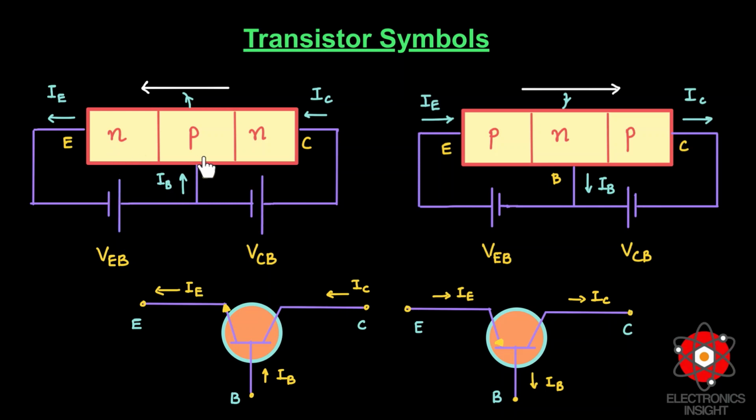current to flow. It is seen that this emitter current almost entirely flows into the collector circuit because of the thin region of base and the lightly doped base region. Therefore, the current in the collector circuit depends purely on the emitter current. If the emitter current is zero, then the collector current is nearly zero.